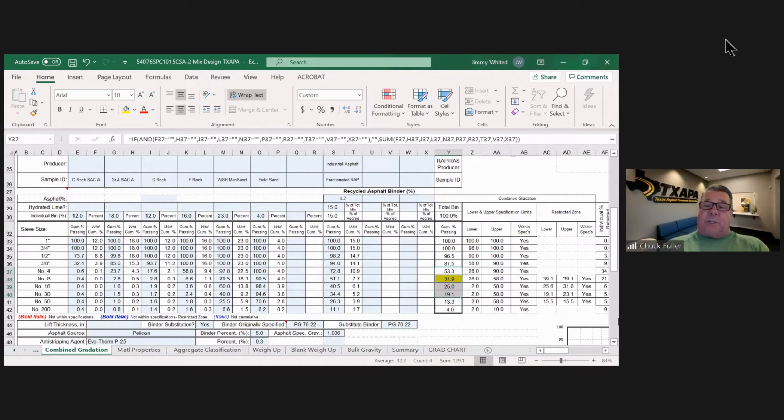And then also, I want you to talk a little bit about control charts, because when you start talking about 23% man sand and your moisture in that man sand goes up, you know that you're going to be struggling some, right? So talk about your control charts that you have out there at the plant, where you do specific gravities, moistures, and gradations, and then chart that material, especially if you're buying material from the outside, because these designs that you're talking about and this new Superpave spec, it is so sensitive to gradation changes. So talk a little bit about that.